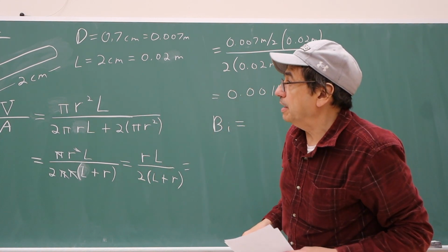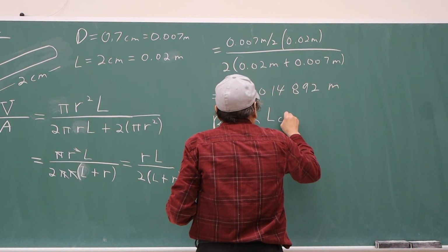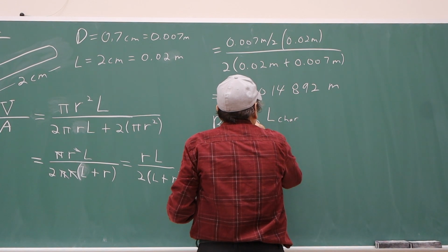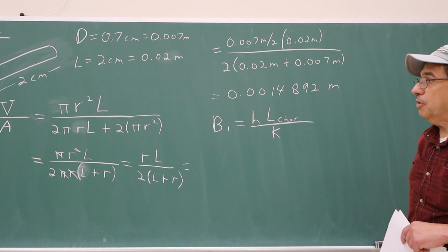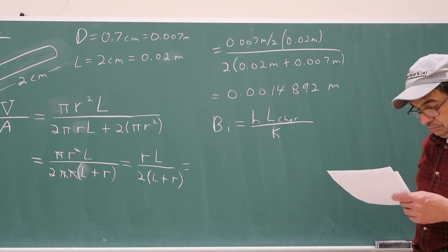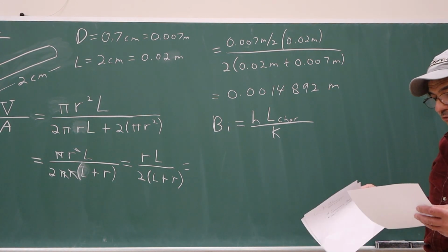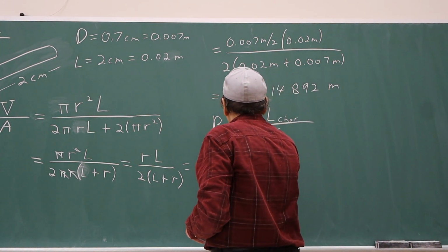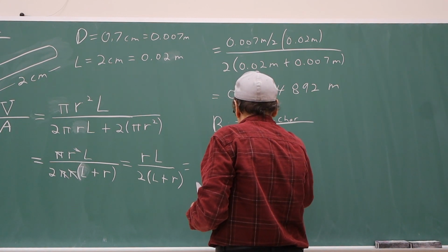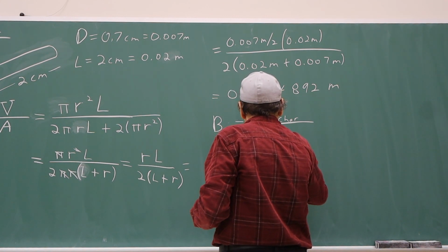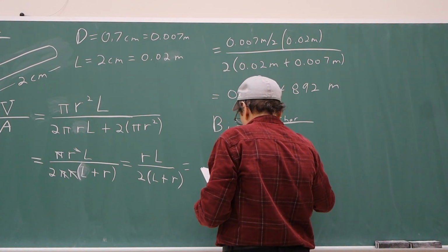That we did a little while ago. It's going to be the heat transfer coefficient times the characteristic length divided by the thermal conductivity. And if you substitute all the values, this was 30 watts per meter squared